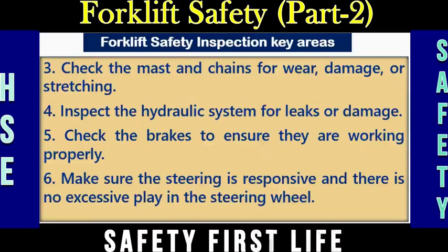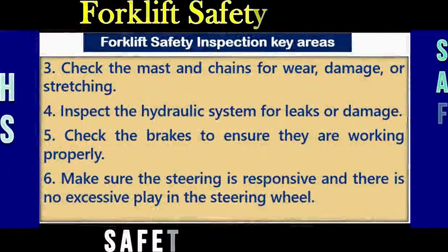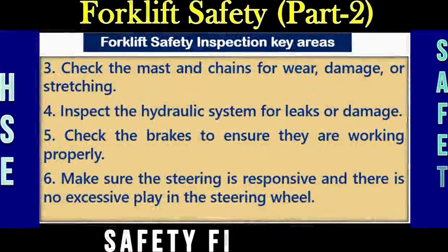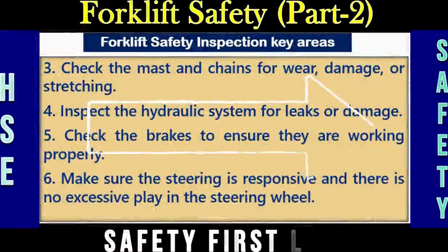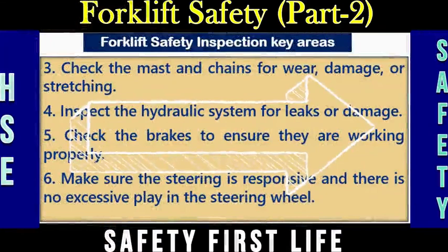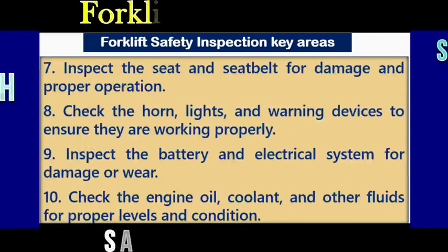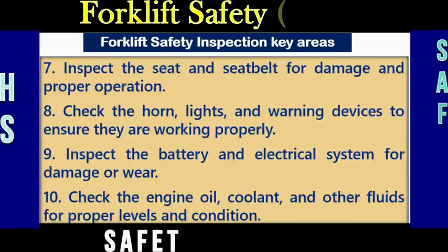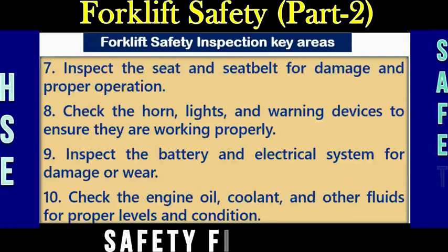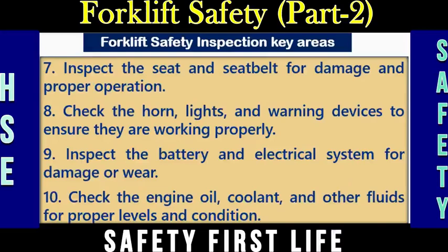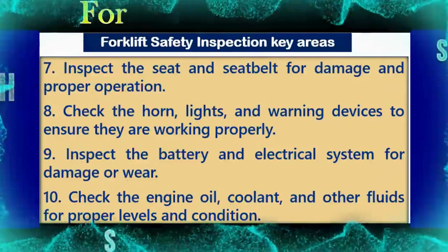Number 5, check the brakes to ensure they are working properly. Number 6, make sure the steering is responsive and there is no excessive play in the steering wheel. Point number 7, inspect the seat and seat belt for damage and proper operation. Point number 8, check the horn, lights, and warning devices to ensure they are working properly.